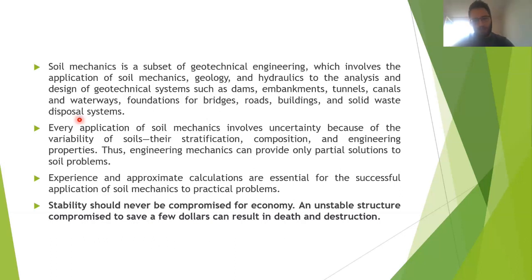So what can you actually do? You can put more emphasis on the soil investigations, put more effort into lab testing, and be sure how you're defining the soil parameters for your design. You're not going to take just any parameters that you got from the lab, because the lab sometimes can give wrong results.